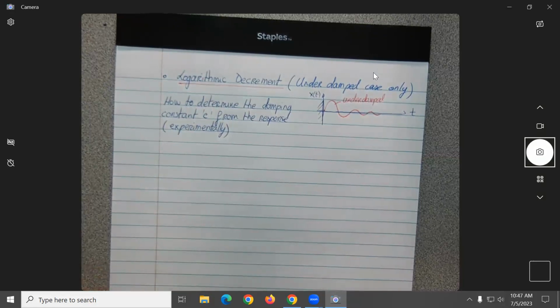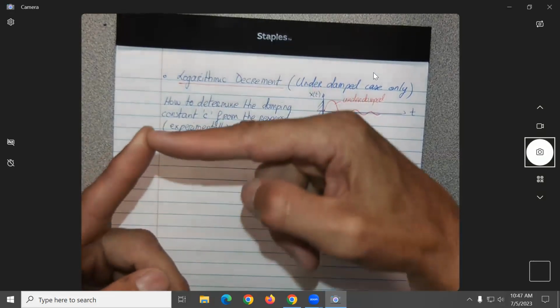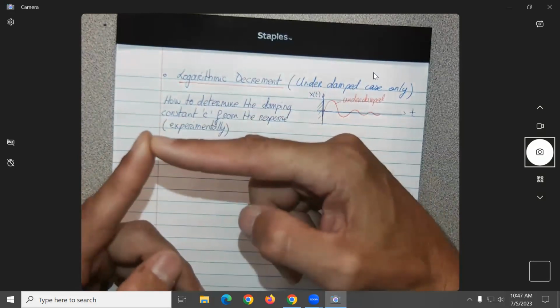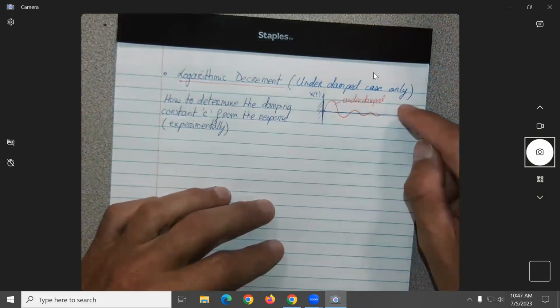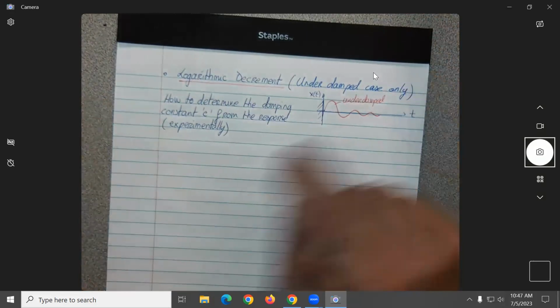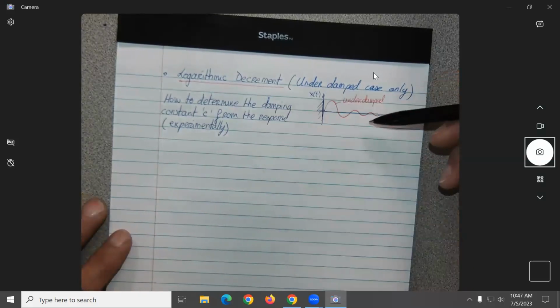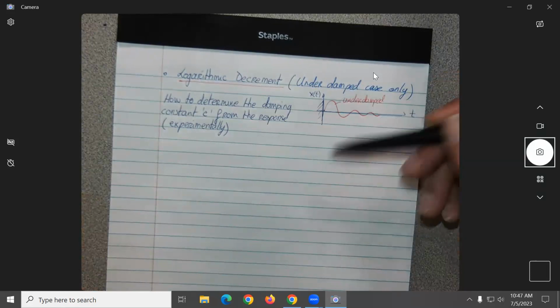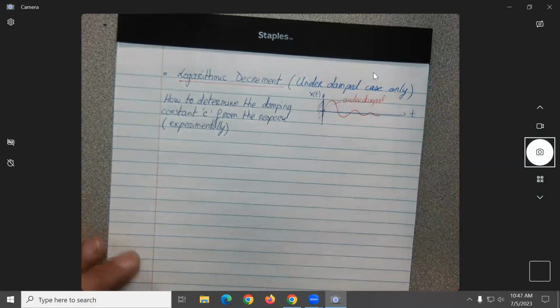If you have a material, you can make it a cantilever, no? You put it at one location, you deflect a certain distance, and you let it go, no? And you can record with an accelerometer, whatever you want, what will be the deformation. Now, I think it will make sense that if you look at the response of the deformation, you should be able to find the damping ratio. So that's basically what we're going to be doing. All right, so let me just redo a figure here.